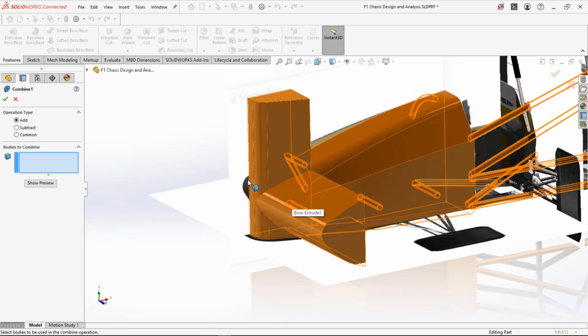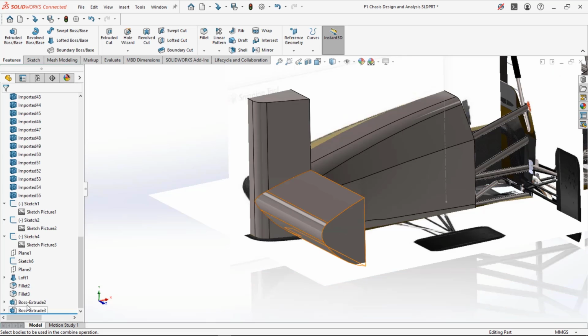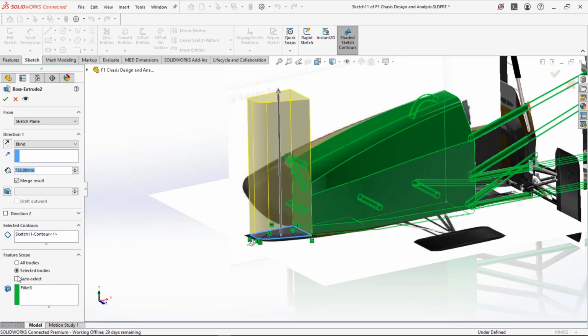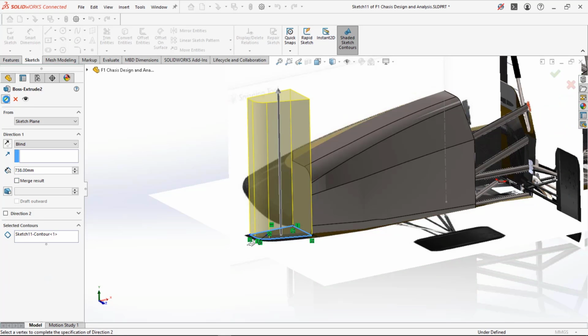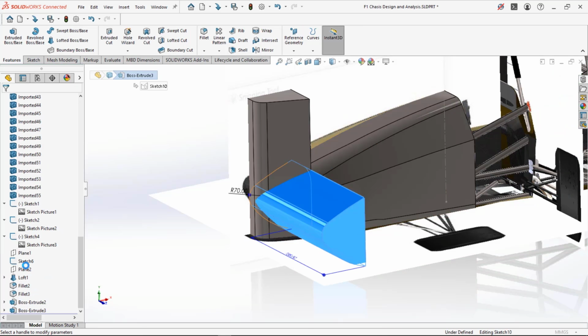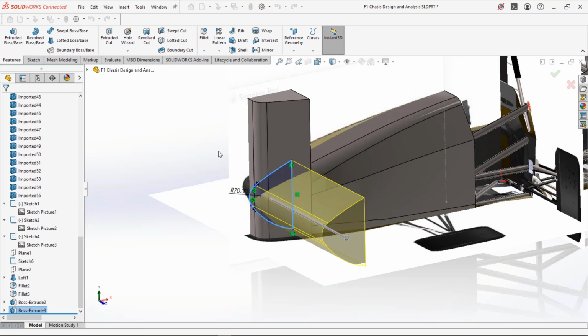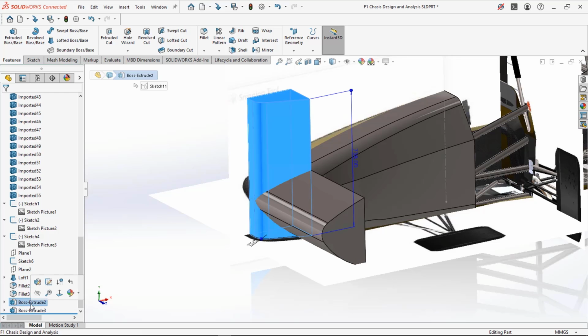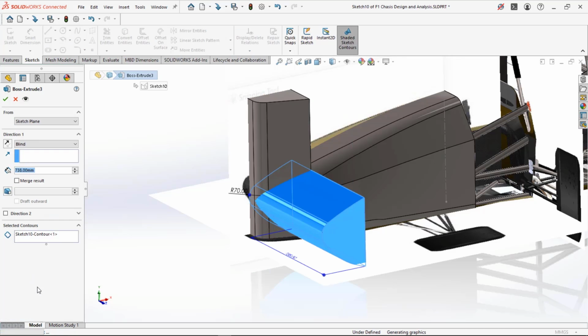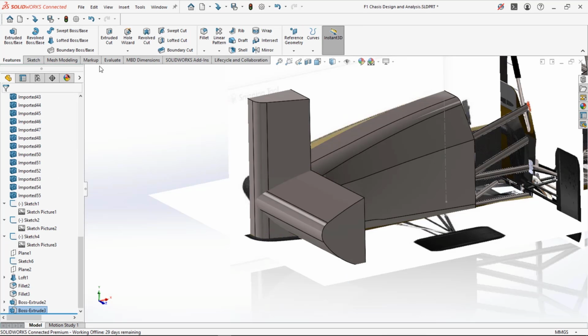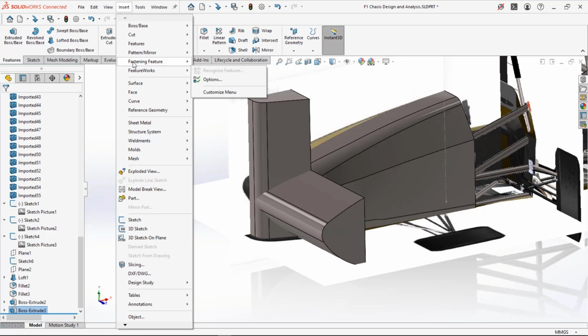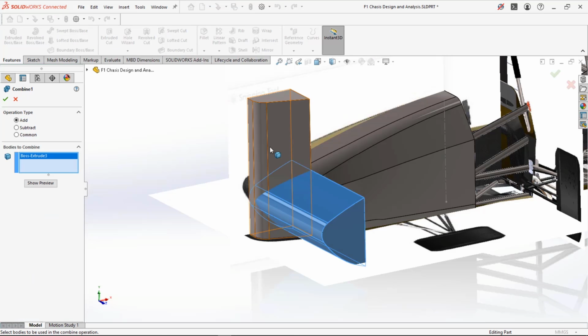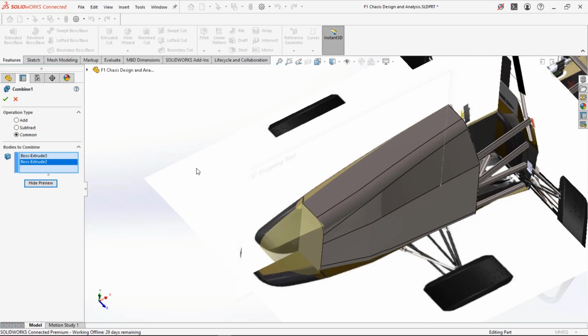Features and combine, as you could see, as it's a multi-body, it's a single solid body, so I need to activate multi-bodies. So I'll just uncheck the merge results so that these two will be separate solid bodies. These advanced multi-body tools will work only if you have multi-bodies inside the model. Yeah, fine. So now you can go to insert, features, combine, and select these two and use the common figure. So this is what you get.